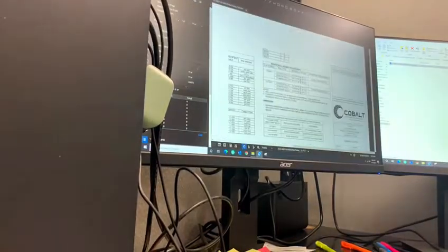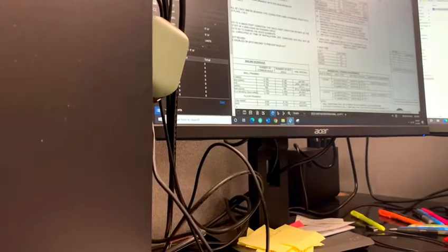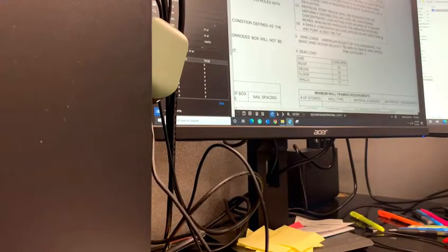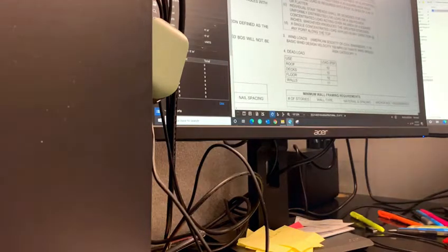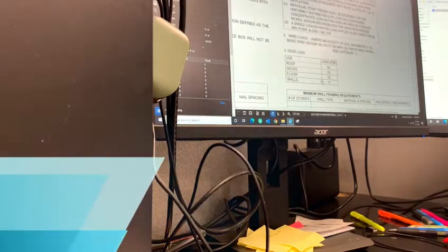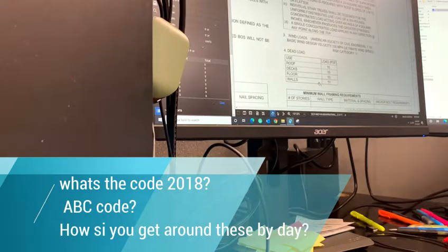This one's in Galveston. Okay, so according to our new codes, the new city adopted codes, the rated wind load is 150 miles an hour. It's a risk category 2, which means it's a more substantial structure, not just a shed. And what's it called? 2018 IBC code?